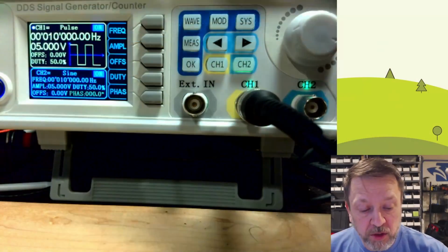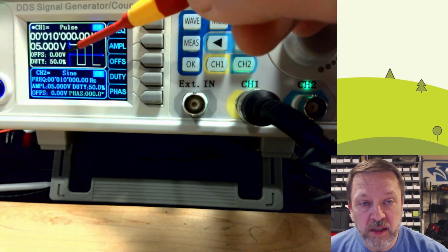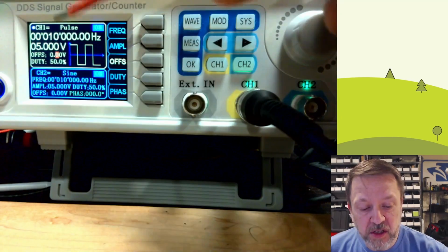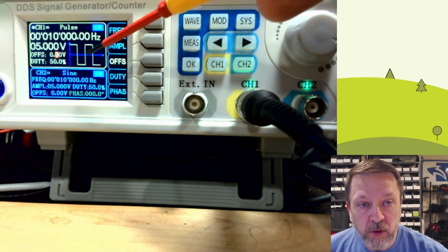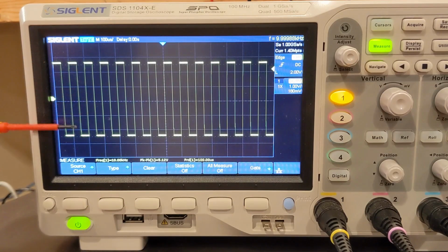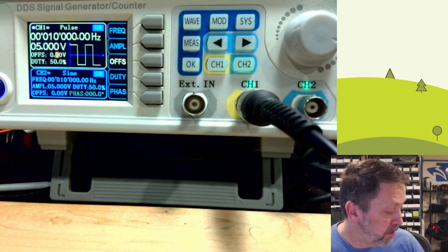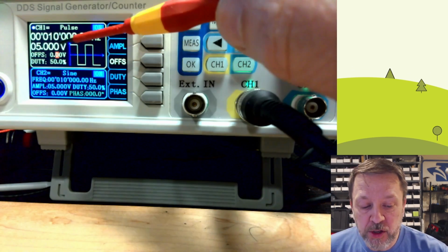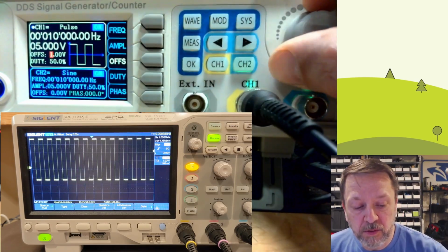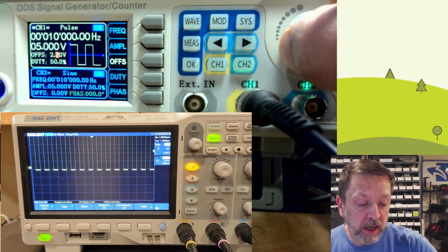To move that, we're going to use the offset, which is this function here, and it's listed right here in this channel. So if I select offset, you can see the cursor moves here. Now, right now, half of the wave is above 0 here, and half is below. So what we want to do is we want to offset it up half of the complete range. If the complete range is 5 volts, we want to move it up 2.5. So I go over, move it up 1, 2, move it over, and then move up a half a volt.